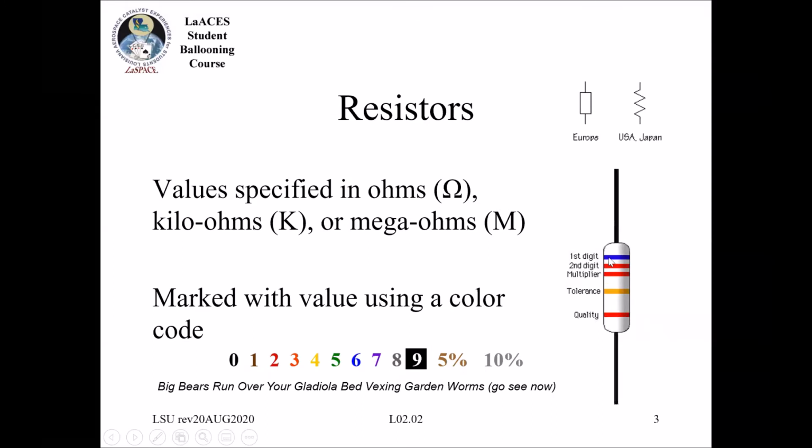Anyway, whenever you pick up a resistor, this is what we call a through hole component, and it's also an axial resistor. There are going to be some different color bands, and this is consistent across all through hole components. So there'll be a first digit, a second digit. If it's a precision resistor, there might be a third digit, and then there's going to be a multiplier. If I were to look here, the first digit is blue, so that's 6. And then this is orange, so it's 62.